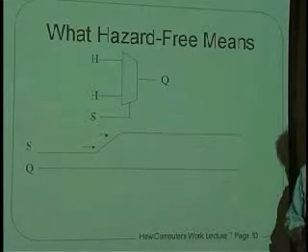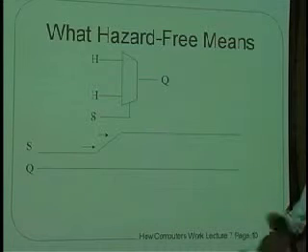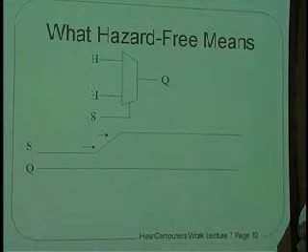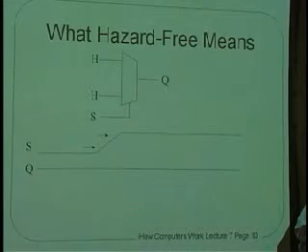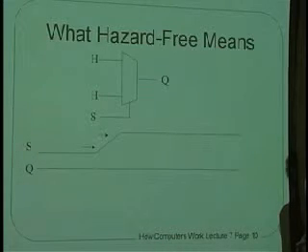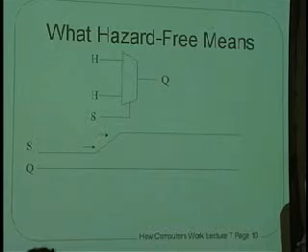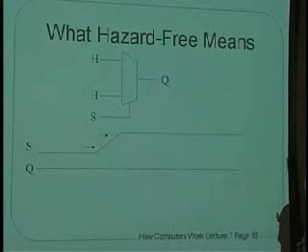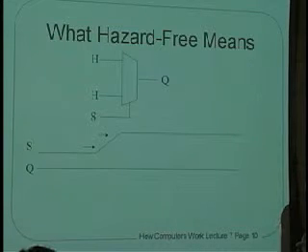It turns out, despite the fact that I've been teaching all about this blue stuff, that if you really cared and you hated the blue stuff, you can build a selector that doesn't do it. I got to this idea of an output that didn't glitch a little bit at the very end of the last class. We talked about a register, a flip-flop, that if it had a high output to begin with, and you clocked it, and it was meant to have a high output afterwards, its output did not go through a little blue zone of perhaps glitching, but instead stayed high.